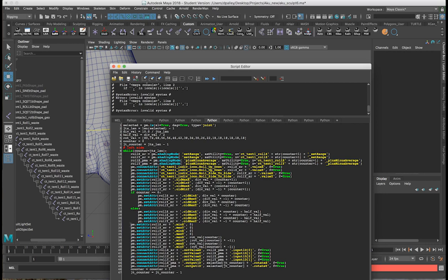And then we set the min and the max for the rotation values for the joints. By default, it's 0 here for the rotations, and then the rotation values for the positive is just essentially going through this list here, and we multiply by -1 for the negative rotations.